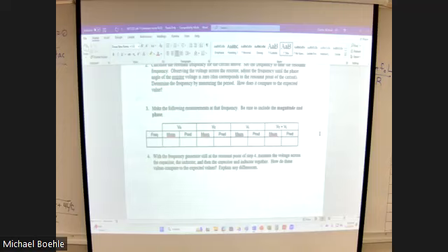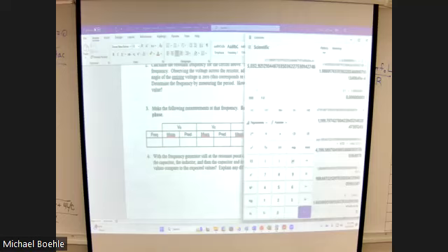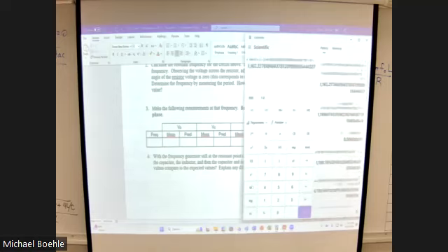Now, at resonance, and we can go ahead and come back here real quick, take that resonant frequency, multiply it by 2 and pi, and the inductance, 0.1, to find out that at resonance, we have a reactance of about 3.16K. Now, what is the significance of that?